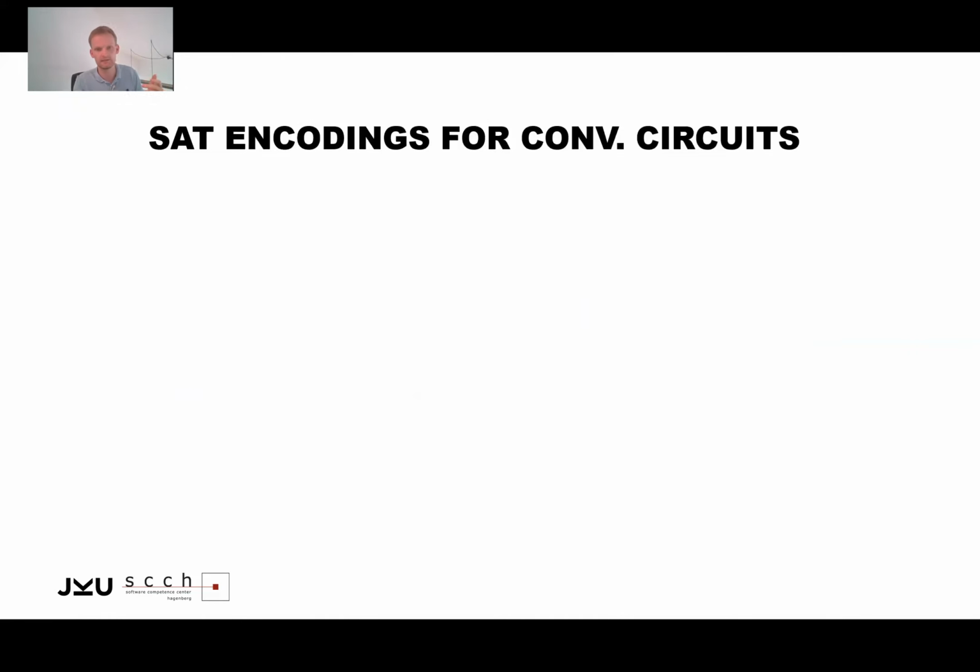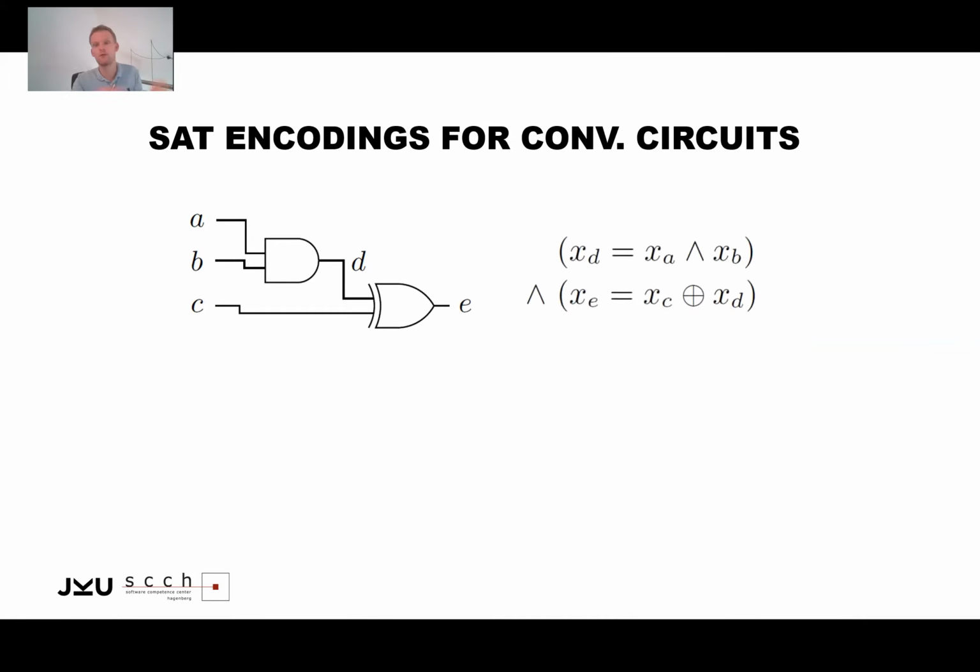And the main idea in all those solutions is that you simply take a circuit and then you encode the circuit in terms of a satisfiability instance, which literally means you represent each signal with a particular variable, and then you enforce constraints which actually realize the corresponding functionality, but now in terms of a SAT instance, of SAT logic.